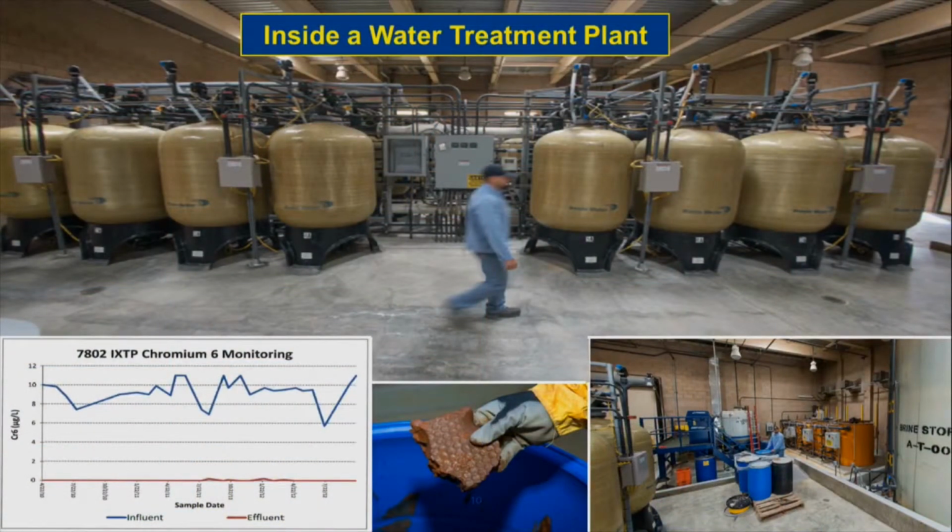Here we're seeing this process. These vessels are filled with a resin that absorbs ions. And ions are chemicals like arsenic and chromium, sulfate. After it's absorbed to a certain amount, you have to regenerate it by running it through a salt solution. The salt solution absorbs what you removed from the water, so the arsenic and the chromium is in the salt. This part of the treatment process then addresses that salt water. We can't dispose of the salt water, so we have to treat it first.